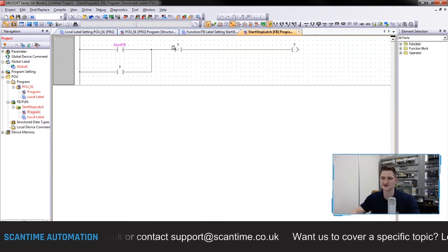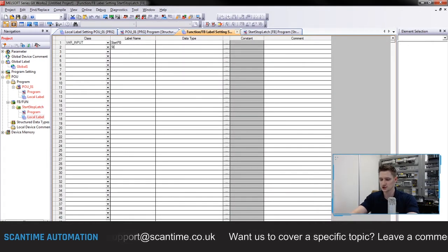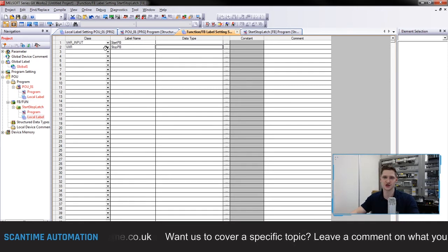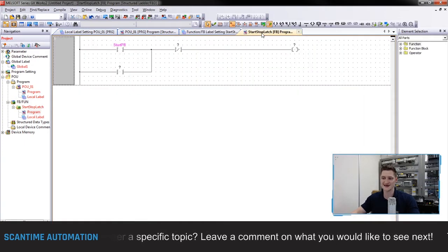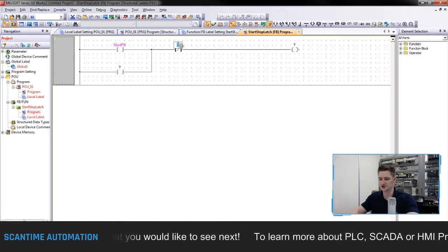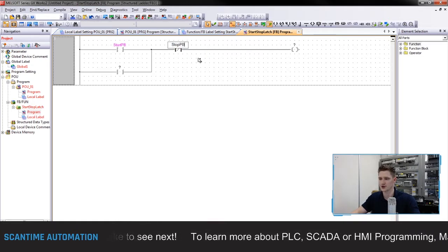The next address that I need to create is my stop PB. So again, stop PB, enter that. It's chosen as a var again, but similar to my start PB, I want this to be a var input, as again this is going to be controlled from the main program. So this is going to be my stop PB. There we go, enter that.